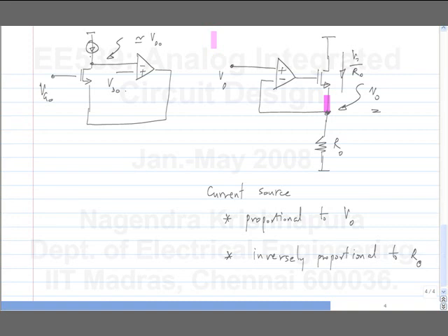See, finally when steady state is reached, this I0 will flow through this transistor M0. So, the source node will get adjusted to a certain voltage. What is that? That is Vc0 minus Vt plus the overdrive corresponding to I0, right? Now, this current has to flow through the op-amp.